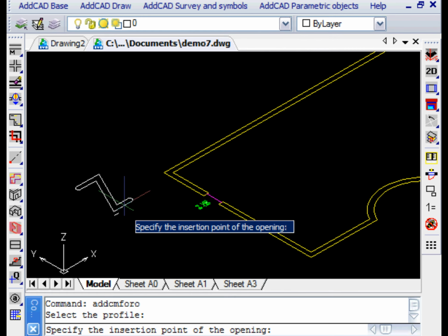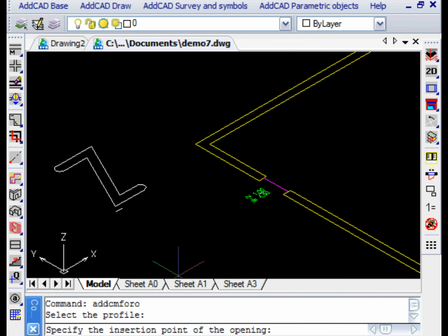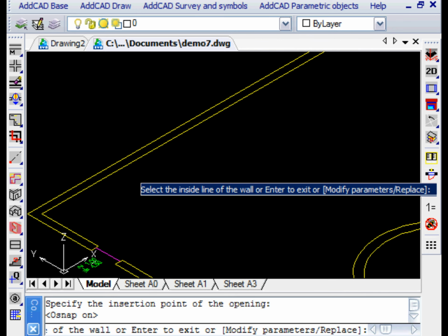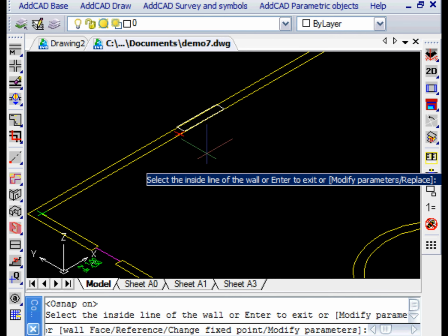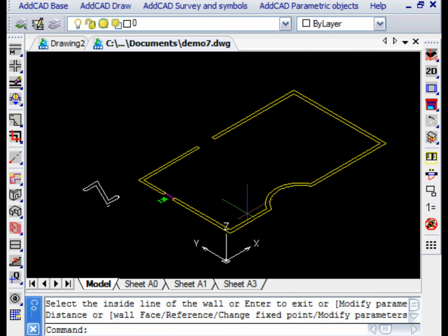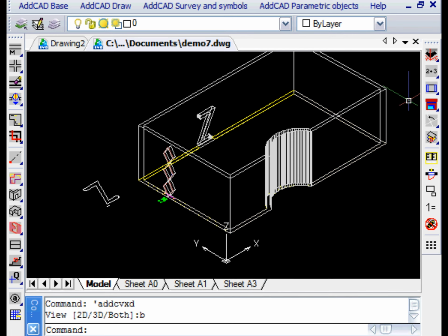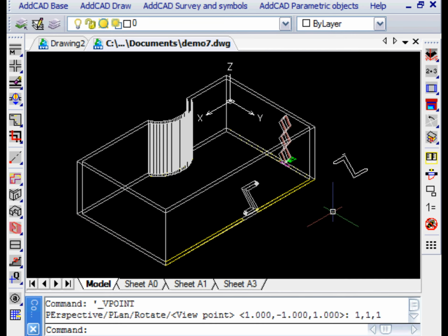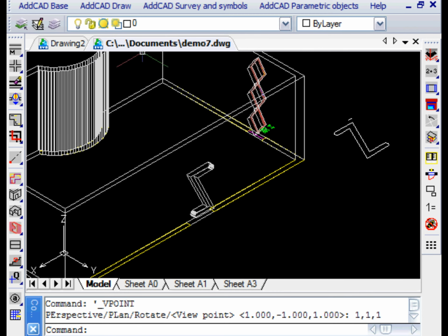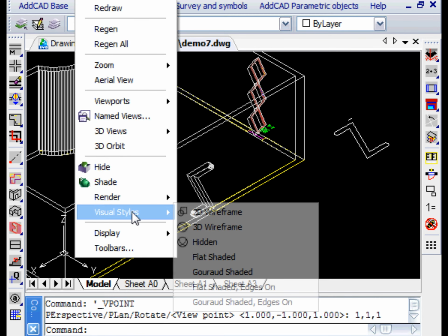The mHole command asks you to select the polyline and a point. This point represents the reference point when we will insert the hole in the wall. In fact, we see that the shape of the hole is placed above the floor level at a distance equal to the distance between the polyline and the end of the selected line.